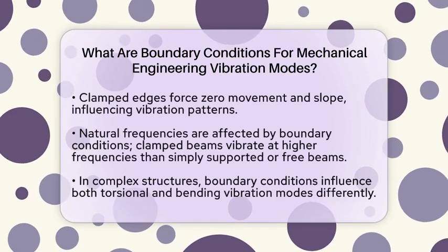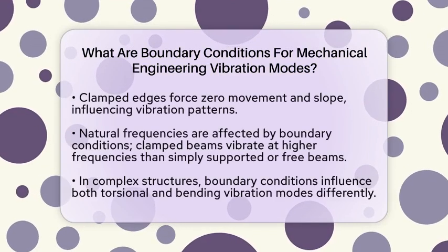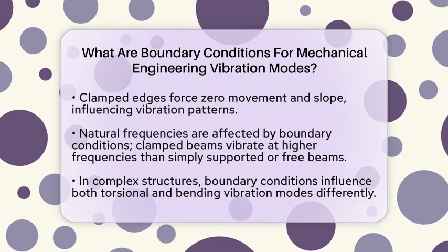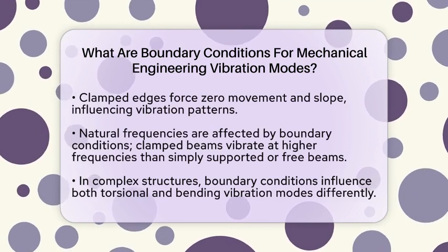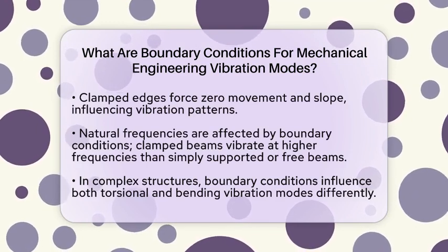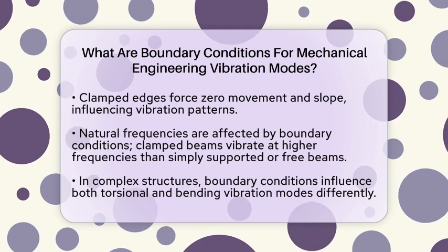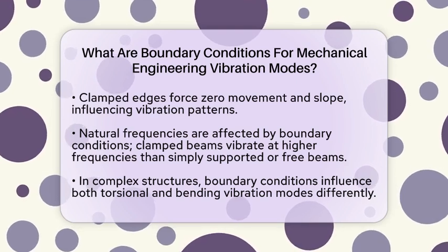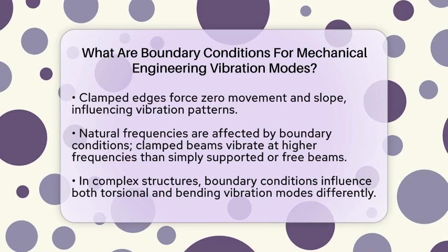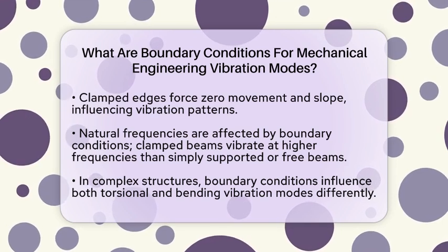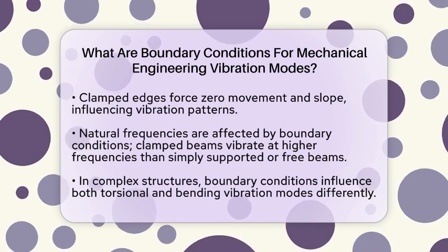Natural frequencies are also heavily influenced by these conditions. A clamped beam vibrates at higher frequencies than the same beam with simply supported or free edges. In more complex structures, such as beams or plates, boundary conditions can influence both torsional and bending vibration modes differently.